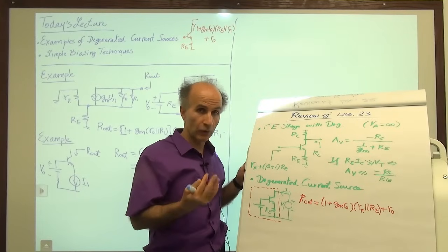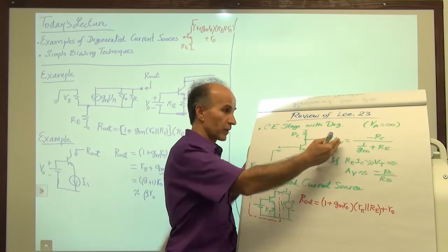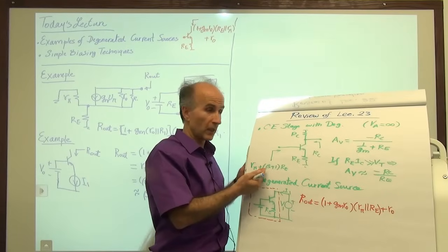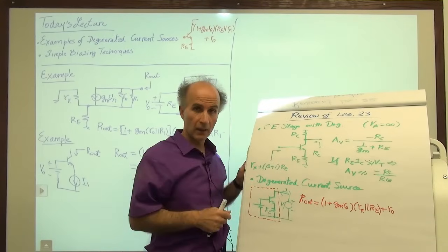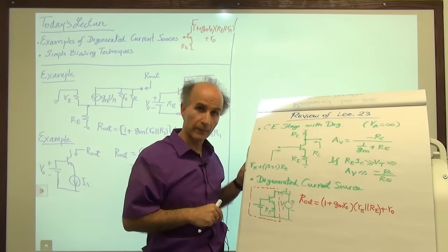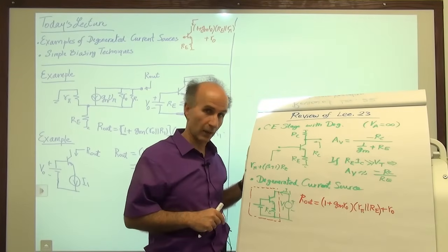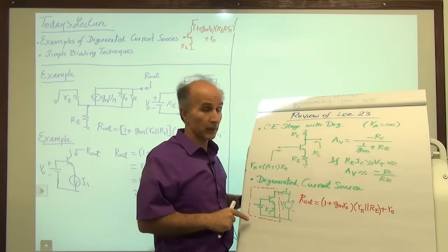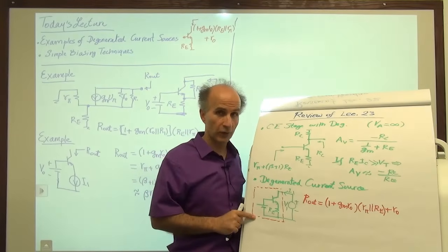In fact, I usually don't remember the equations for the voltage gain and the input impedance if the early voltage is less than infinity. I would have to either derive it quickly, or go back to my notes. That's why we don't usually teach them in undergraduate courses. But it's not a big deal. You can always sit down and derive them if you're interested.